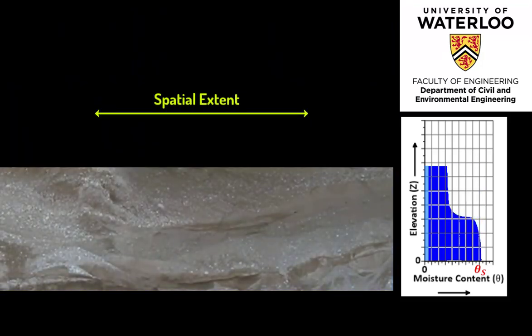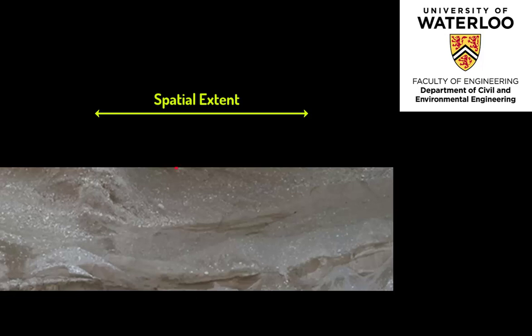Spatially, it is further noted that any particular soil moisture curve and quantification of the infiltration rates is only considered representative for a given geological setting, moisture conditions, land use conditions such as forested, agriculture, or terraformed, for example, topography and vegetative cover. A broad range in values and rates can exist within the same geological setting. Here we will investigate the infiltration characteristics of a small mesoscale location of approximately 20 centimeters in diameter.